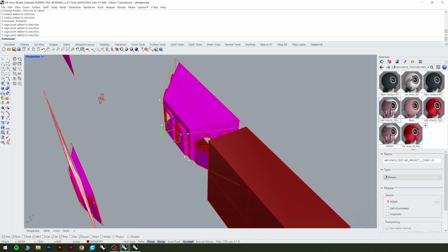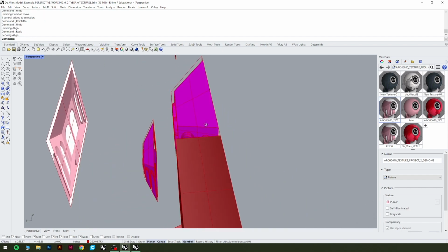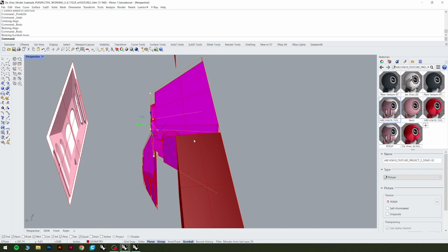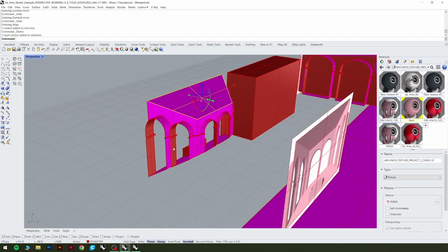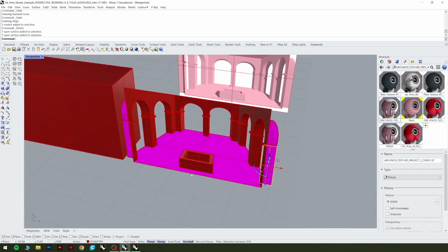But I think you can also just delete the cage. Let's see. Yes. So there we go. You can just hit escape. You'll see that the dots go away. And now it's like, oh, I can't edit it, but you hit F10 on your keyboard. That brings it back. You can also type in underscore points on. Okay, there we go. Make sure you don't mess yourself up. Hit escape a few times and then just delete that cage. And now this thing is locked into its position.